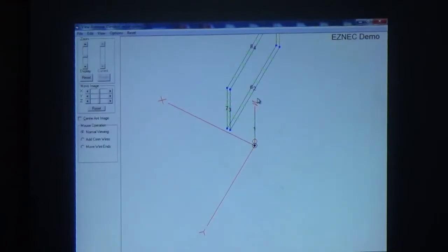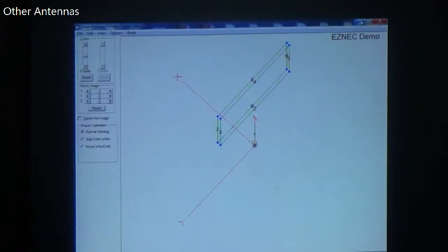But as far as close space wires and loops, the original quad loop was, what was his name, Clarence Moore, down at HCJB. When he applied for his patent back in 1930 or 39 or something like that, it was not a single wire, it was 2 wires. And the difference between a single wire loop and a 2-wire loop is just feed impedance, just like a folded dipole. It doesn't do anything for gain.